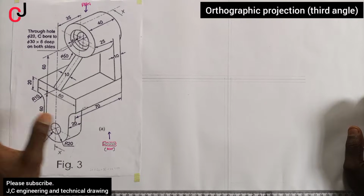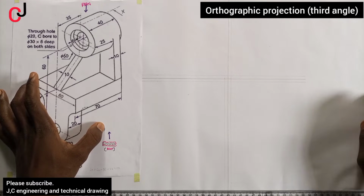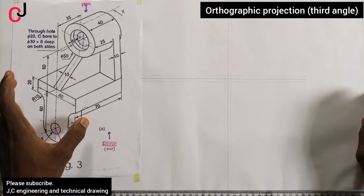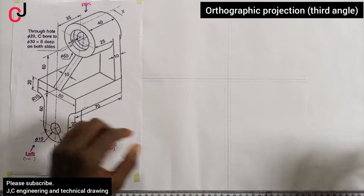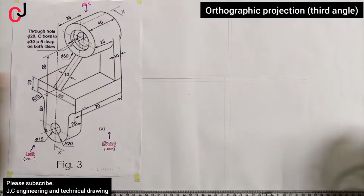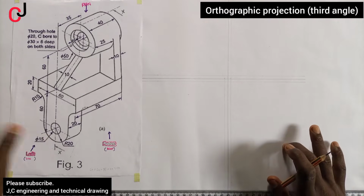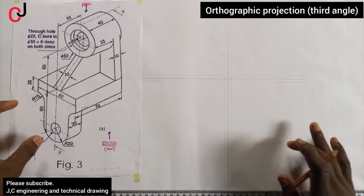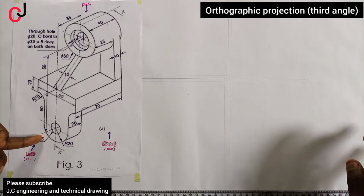Today we'll be presenting our isometric diagram into third angle projection. So the first thing we do is we'll represent our side view, our front view, and then our plan. So we'll be starting from our side view, this place. So we know the total height. First of all, while looking at it from our side, we check the total height